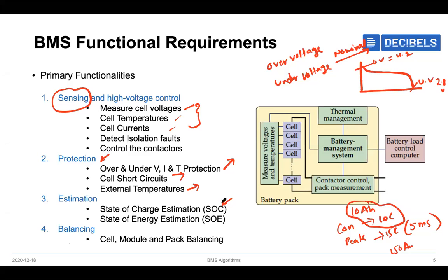Also, this SOC plays a very important role in cell balancing, because there are two strategies that we'll be using for balancing the cells. One is a voltage based strategy, and another one is an SOC based strategy. So there it will play a very important role. If you're not accurately estimating the SOC, then your cell balancing will not happen properly.